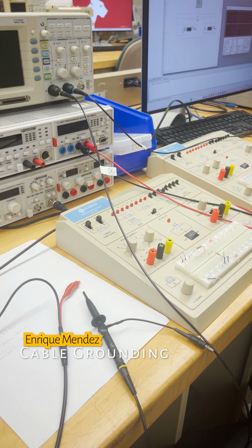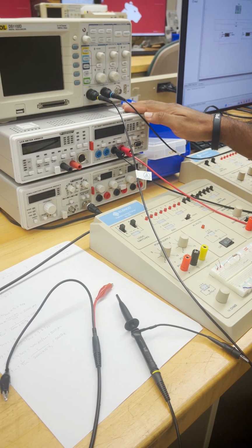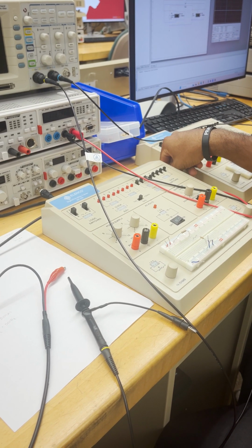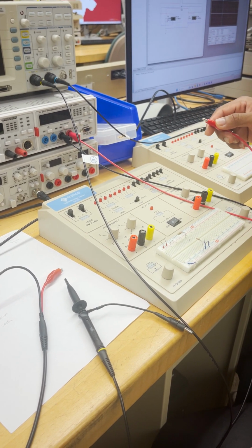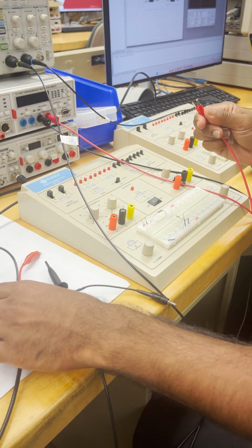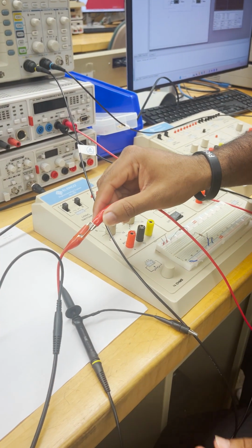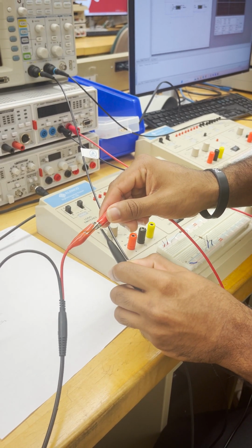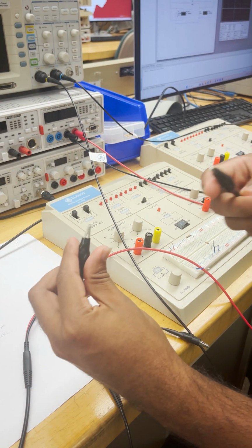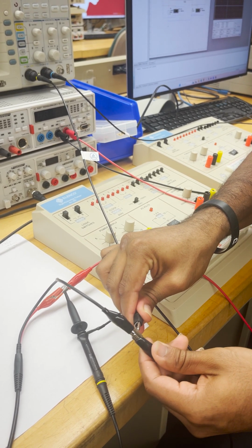Okay, so this is the setup for our measurements on our function generator and oscilloscope and our DMM, so that we can set the correct voltage that's going to be put into our circuit. First, we're going to take the cables from our DMM positive and function generator positive, match those together, as well as the positive from our oscilloscope probe. Then we're going to take the negatives from our function generator and the negatives from our DMM, connect those together, as well as the negative from our oscilloscope probe.